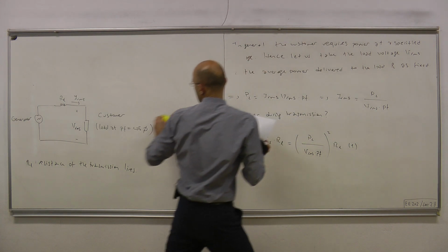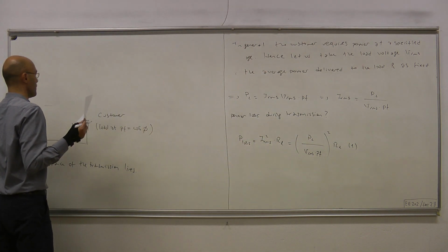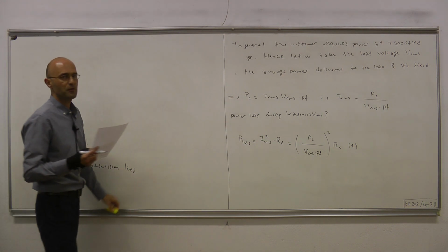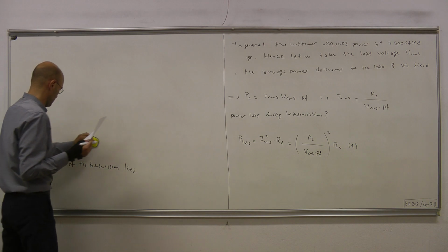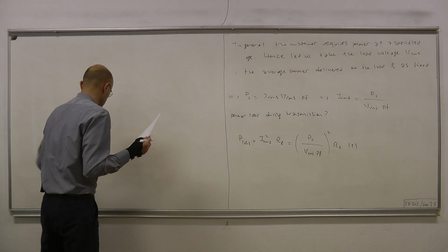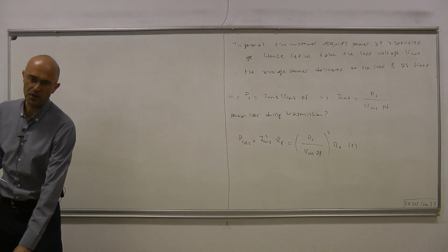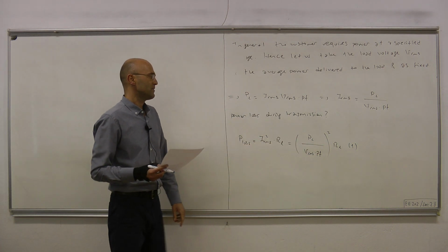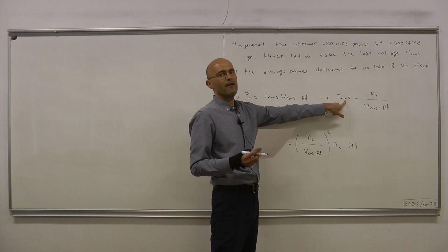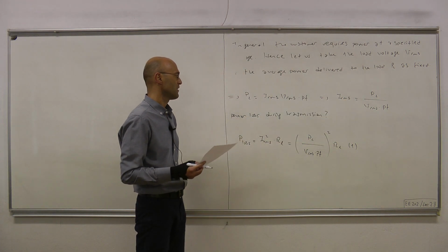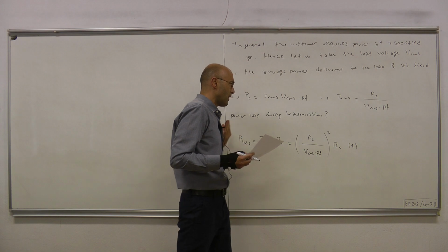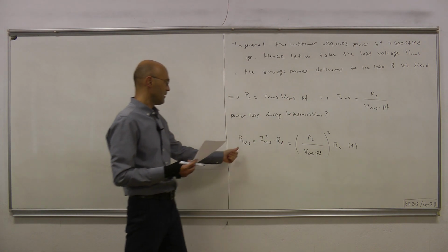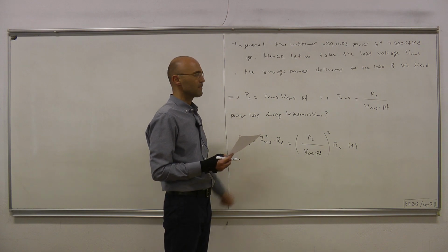And if you look at equation 1, we see that if power factor is small, for instance something close to 0, the denominator becomes small, and in turn the RMS value of the current increases. As a result, large current travels through the transmission lines, and there will be much loss during transmission.